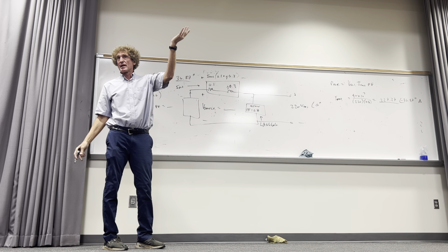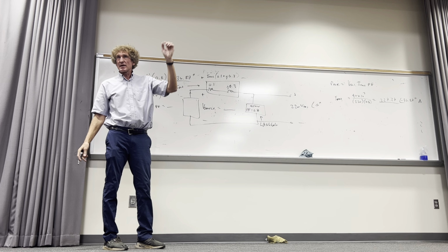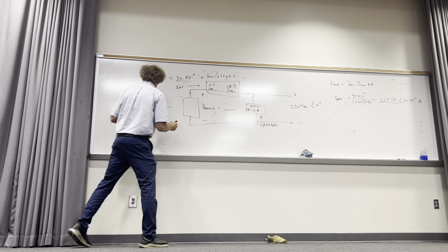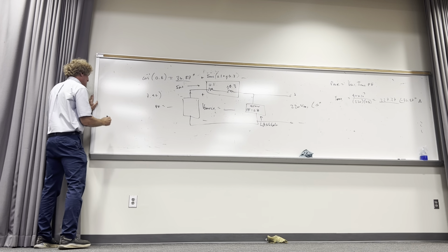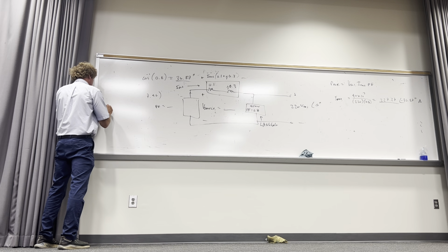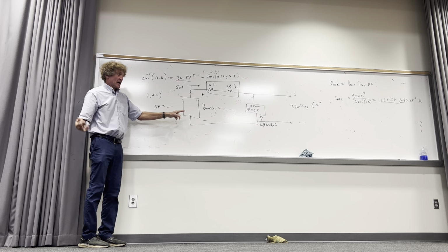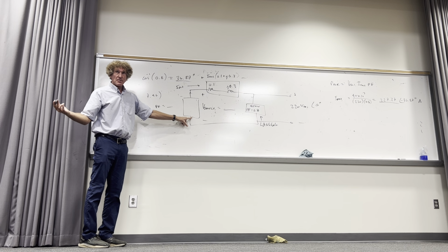How many do? So let's go ahead and get this voltage right here, V source. That's minus to plus. So what would V source be? Well, what would I do? The way I do it, I start at the negative, right? We know the voltage around any closed loop sums to 0.